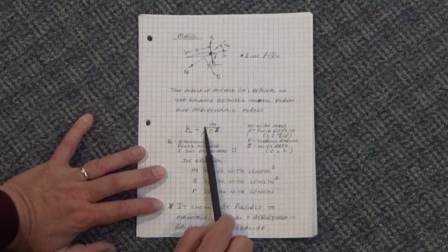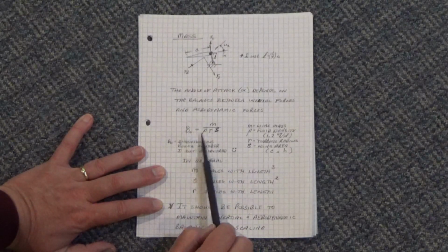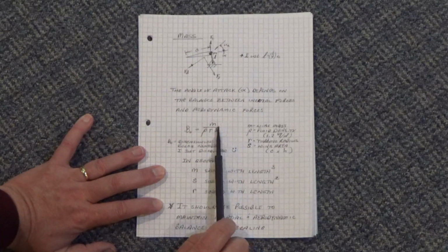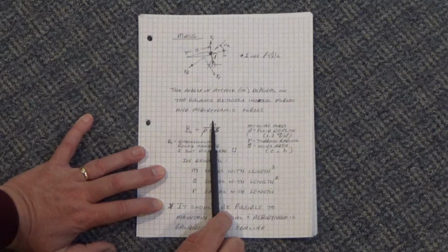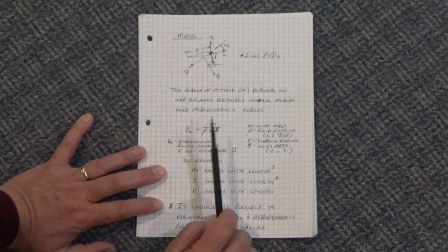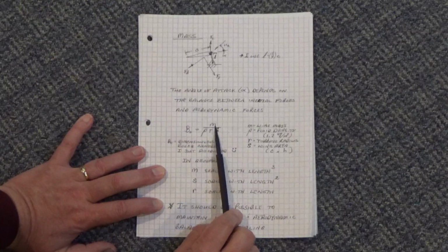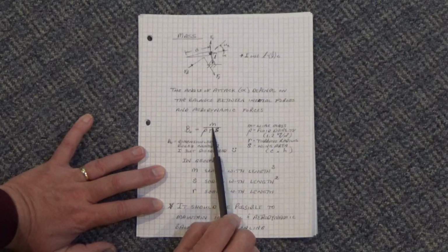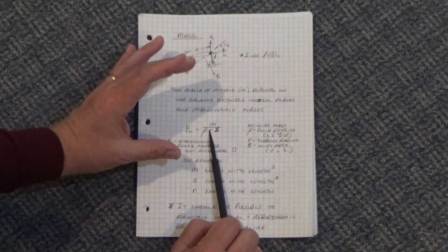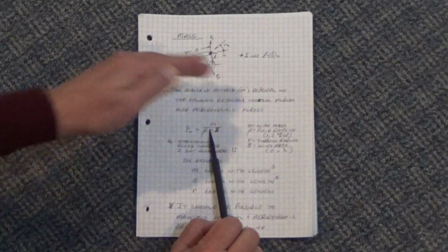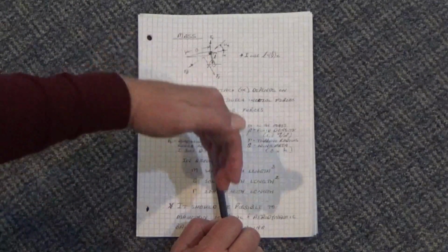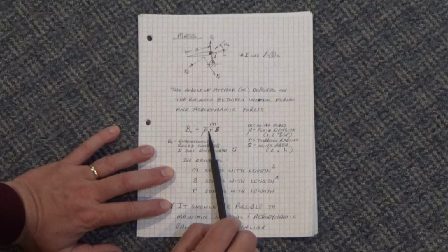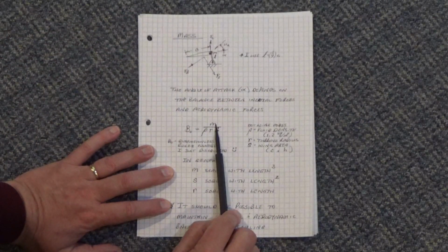This ratio comes up here, and I'm just calling it a Bosch number, BO, just for grins. And it's the ratio of the inertial forces to the aerodynamic forces. So the inertial force is related to the mass, and it's also got this factor R in here because as you go with smaller and smaller turbines, that's got a higher and higher amount of acceleration because you're going in such a small radius, and so that actually affects the inertial forces too.